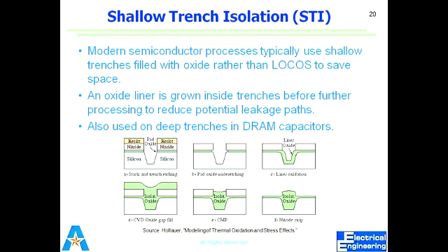So this is the last thing, that is shallow trench. One other method that is used to avoid that bird's beak is shallow trench isolation. In this case, as you can see from here, first of all we drill a trench. After that we etch the underneath oxide, the pad oxide, under etching. After under etching we grow the oxide layer, and after growing, what we do? CVD, chemical vapor deposition of oxide. So here we don't grow, we deposit.